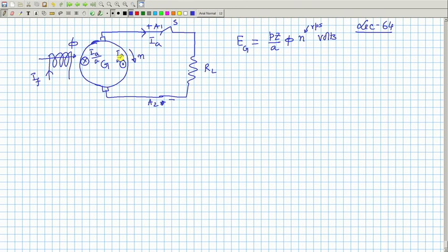And if they carry current in this direction, then by applying left hand rule, we observe that the electromagnetic torque will be in this direction. Direction of rotation is decided by the prime mover torque, T prime mover. And if these two are equal, then only the generator will run continuously at a constant RPM, delivering power. Any imbalance between T E and T PM will either accelerate or decelerate the generator, and this will happen when the machine is under transient conditions, and finally, the machine will always seek to reach a state where T E will be equal to T PM.